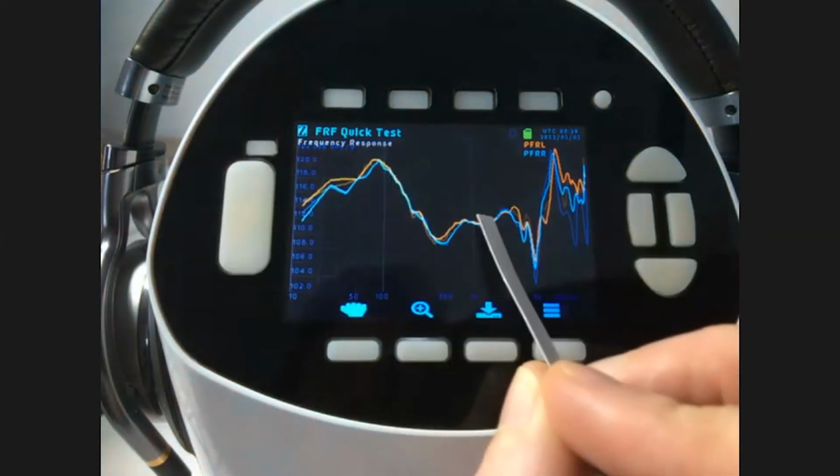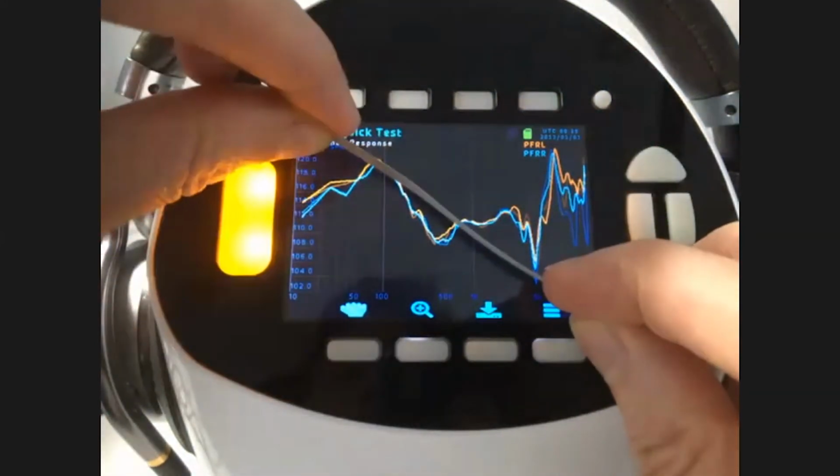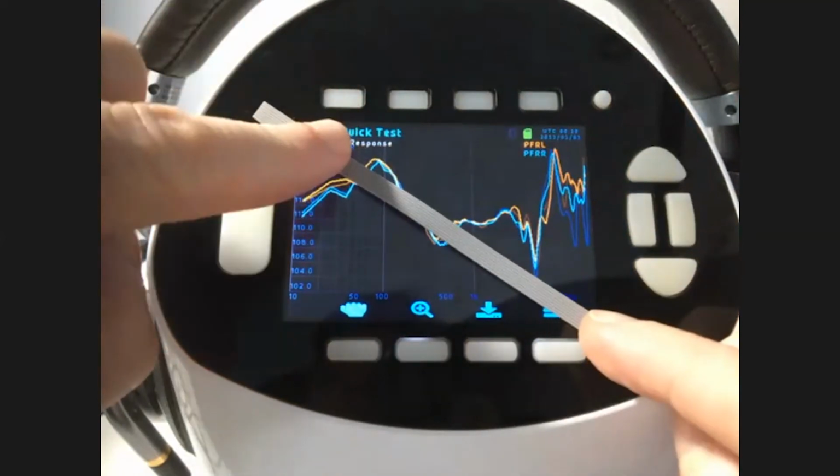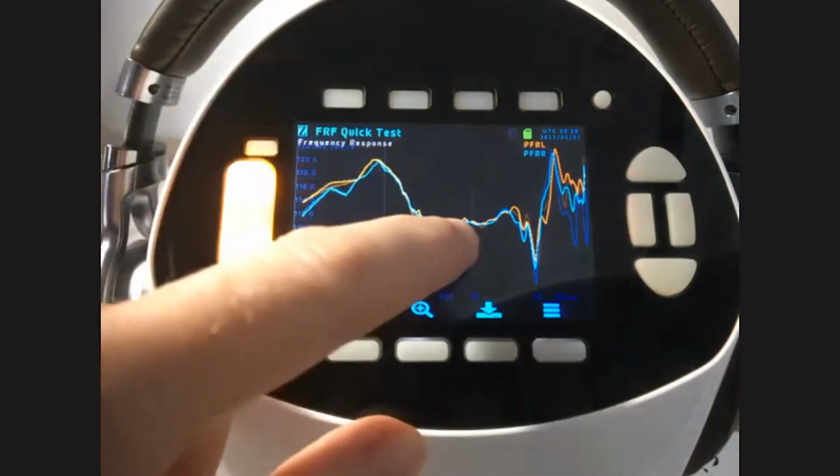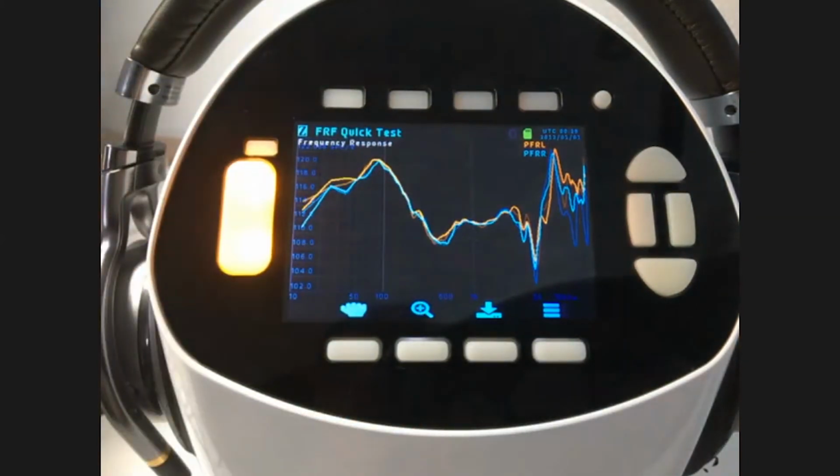For over-the-ear headphones, at some point we had that downward slope for the earbuds, right? Yes. When you've got a larger acoustic volume, at some point you hit a bottom where it stops sloping down and goes flat. And that's where it gets to the point where it's becoming like a speaker, because that volume compared to the frequency is largish.